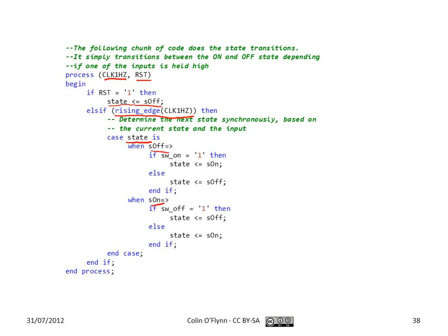If it's S off, it checks the value of the on push button. If the on push button is 1, it updates the state to now be on. Otherwise it does nothing, and stays in the off state. If the off push button's 1 and we're in the on state, then we likewise flip to the other state.